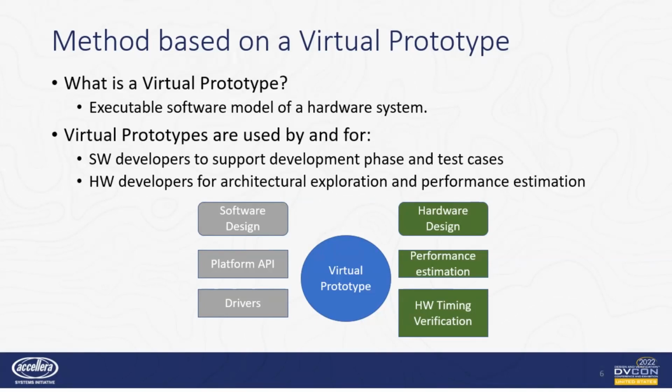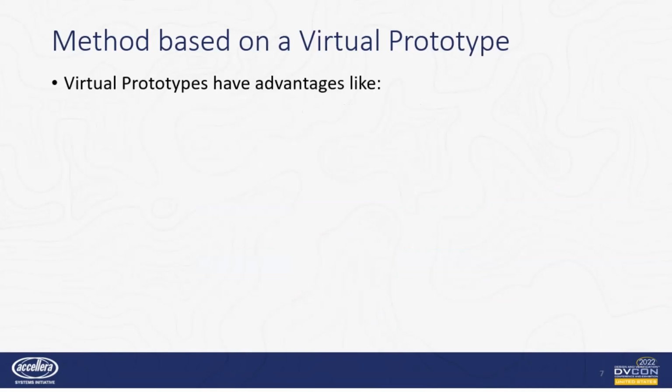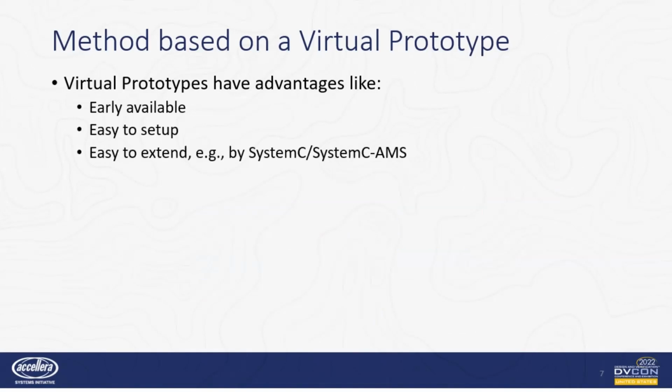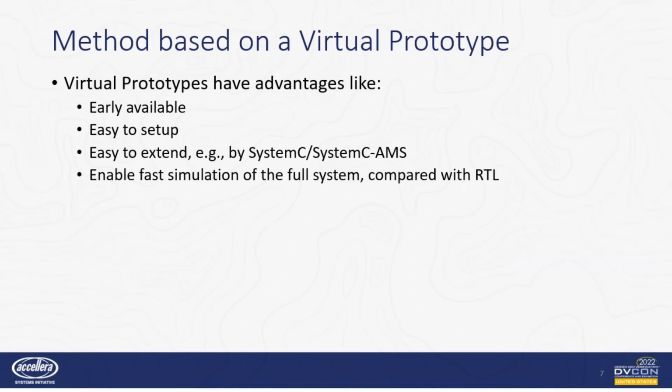The advantages of virtual prototypes include hardware-software co-design, supporting software development tasks by adding more hardware details to increase the modeled functionality. This expands the ability of the system designers to do hardware architecture exploration and its trade-offs. Virtual prototypes also have advantages like they are early available in the development process, they are easy to set up, they are easy to extend, for example, by SystemC, they enable fast simulation of the full system compared with RTL, and they reduce the hardware dependency.